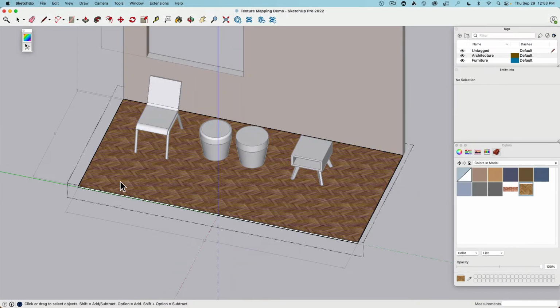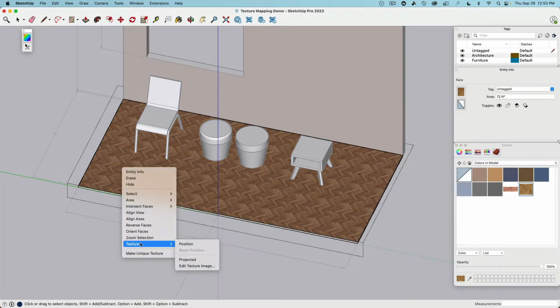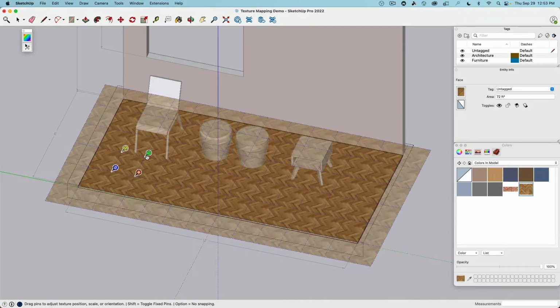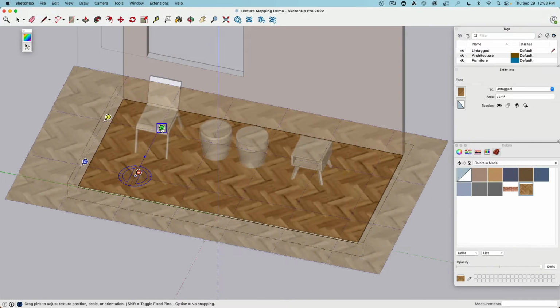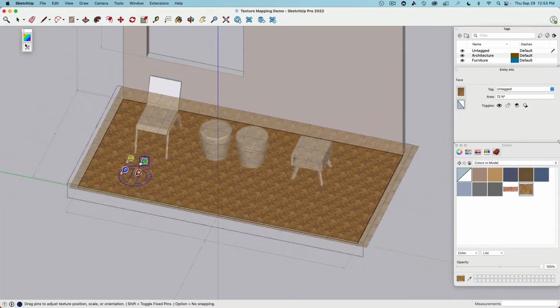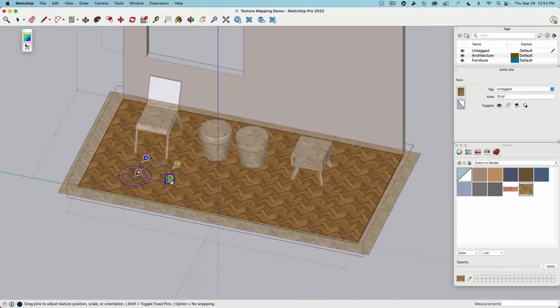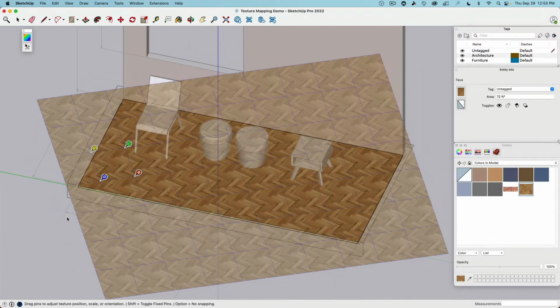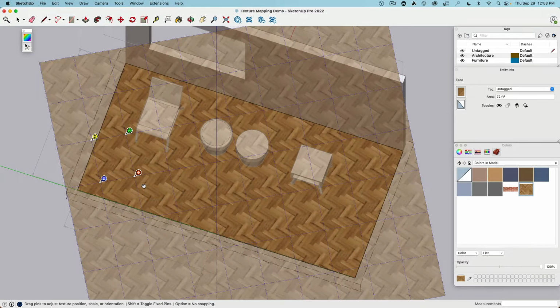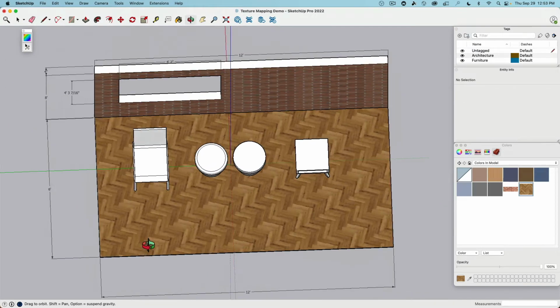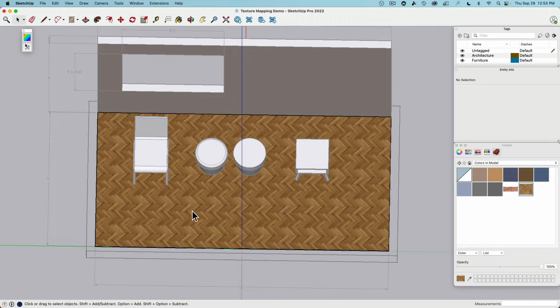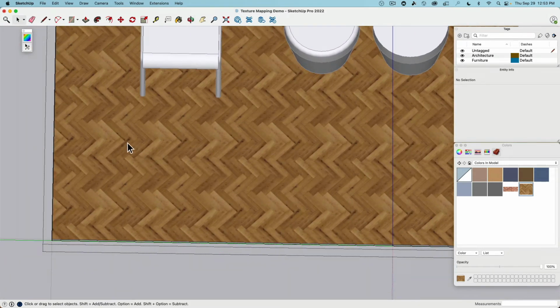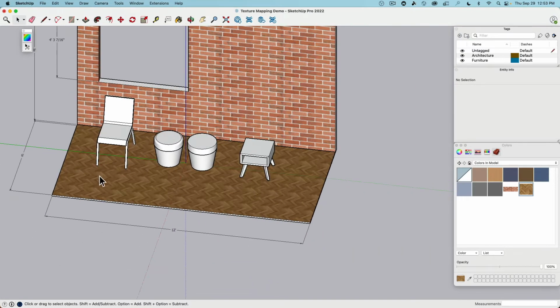It's really important. I could also, as an alternative, have gone into the group, edit, right click, position, and then you see here there's this rotation tool, and with that I can scale this up or I can scale this one down. I can also rotate it. No, like make this tile over it. Talking about tiling, you see each is actually one tile of an image. And this image is made to be seamless, so we can't really see bad tiling. Actually, we can see repetition 1, 2, 3, 4, 5, 1, 2, 3, 4, 5.